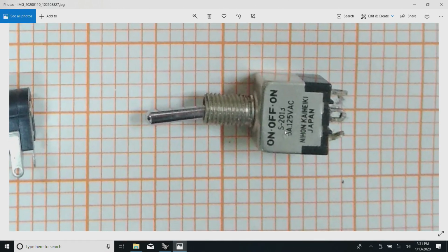design. You see here, this is slightly different from what I had shown you earlier. In that case, I had shown you printed wiring pads, and in this case the similar switch has a soldering provision. And typically with all these small things, very rarely is a connector used, directly things are soldered here, and probably these soldered points are mounted on the printed wiring board by some mechanism. Very rarely do you have a separate connector and all that.